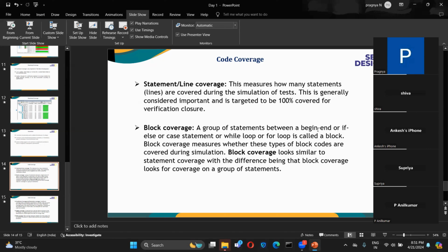If the self-checking TB is written only for that particular test, it will be applicable only for that particular test, right? But for an assertion, if you include that scenario in the top level, wherever you want to call that kind of assertion in a particular test case, you can include it. Through that, you can verify it. So you can think of it as self-checking also, but we don't call it that way, because the purpose is the same, right? Yeah, okay, thank you.